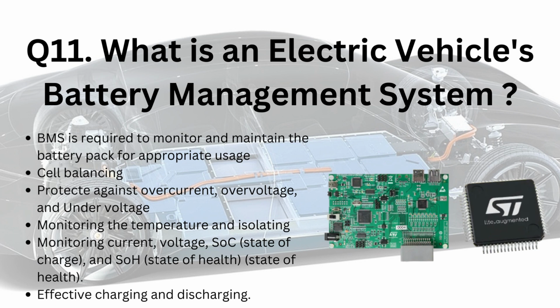You can see the key responsibilities of BMS, like cell balancing. The battery pack is protected against overcurrent, overvoltage and undervoltage, and it monitors the temperature and isolates the battery if it rises beyond a certain threshold.